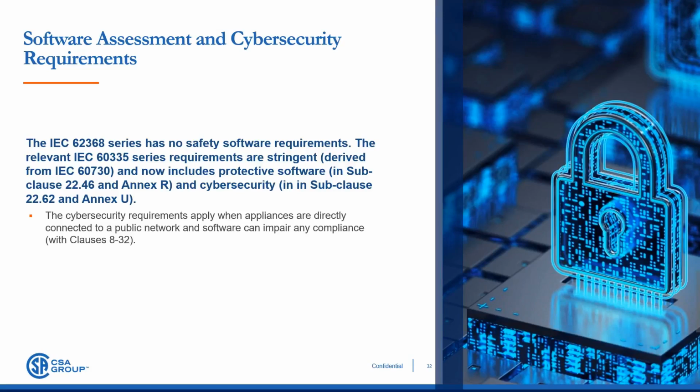not only for safety-related protective software, but also implements the same requirements for software that, if changed, would impact compliance with any major part, clauses 8 to 32, of the applicable IEC 60335 standards. These innovative requirements have yet to be implemented universally across other similar category-specific standards. It is important to highlight that these requirements currently apply to appliances directly connected to a public network.